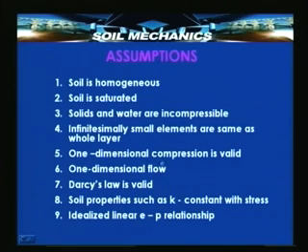Now, the mathematical derivation is based on a number of assumptions, many of which are already familiar to us. We have already assumed that the soil is homogeneous, the soil is saturated, soil and water are incompressible, and small elements are similar to the entire layer because the soil is homogeneous. We have already defined that one-dimensional compression is valid, and one-dimensional flow takes place when load is applied. We are now finally also adding another assumption, that the properties of the soil, particularly permeability, remain constant with stress. As the stress changes, the permeability does not change.